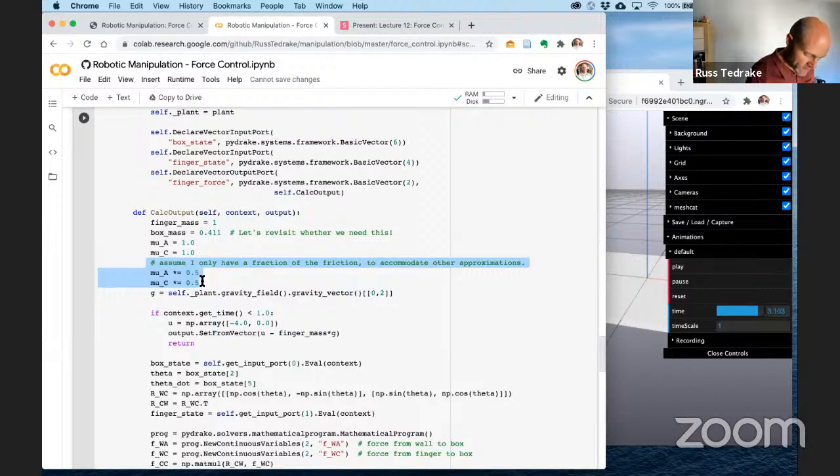When I did it in my teleop, the first thing I would do is drive the desired position somewhere into contact here. That produced some reasonable force. And then I started driving the desired position of this. So you can think about this as a spring pulling my finger, right? And at some point, this will start moving up as I pull this up.